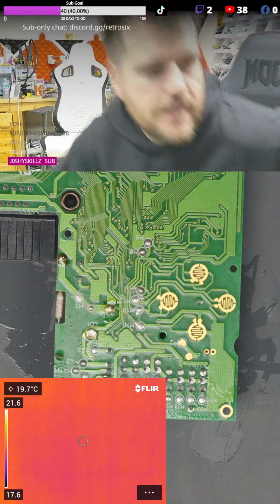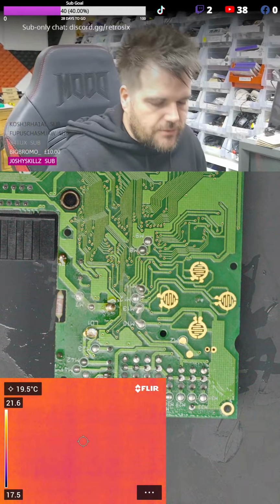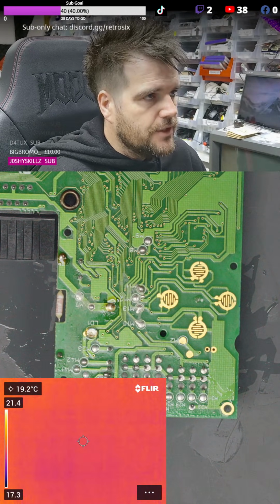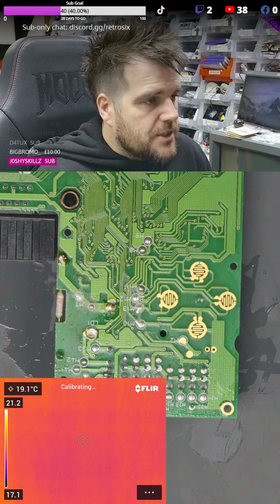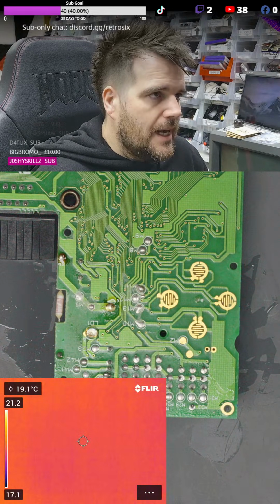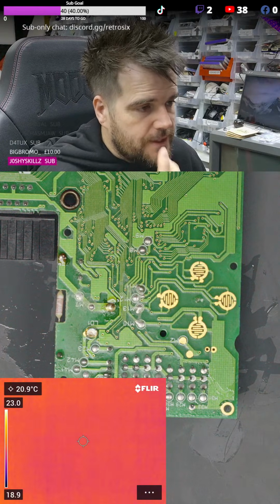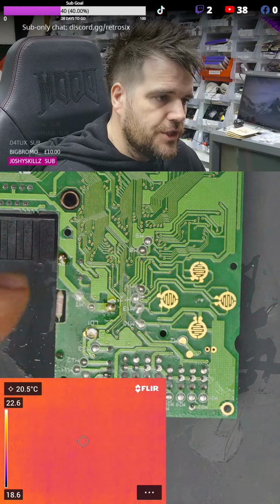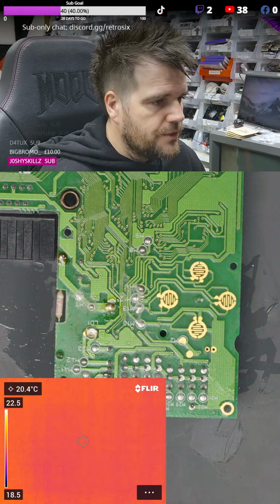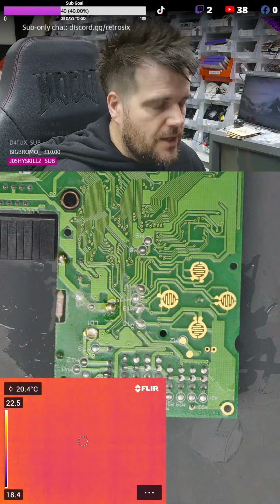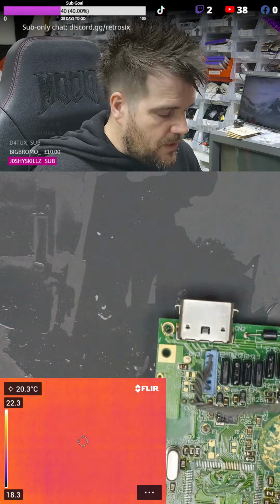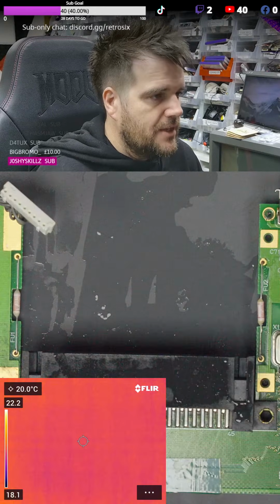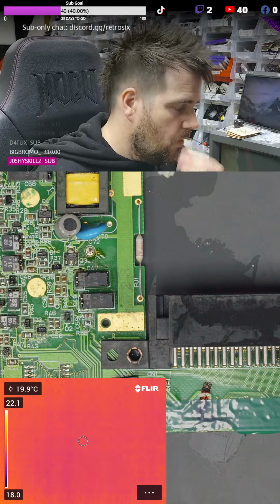Really, that's most methods of finding shorts: resistance for one, IPA for another, bench power to see the current draw for another, and thermals for a fourth detection method. Now, the benefit with the bench power is you can probe around and inject voltage into certain rails. So what I'd normally do is get 1 volt and inject it into each rail and find where the short is. Now, there are some things to look out for. There's also different kinds of shorts, but let's first just cover one thing to look out for.